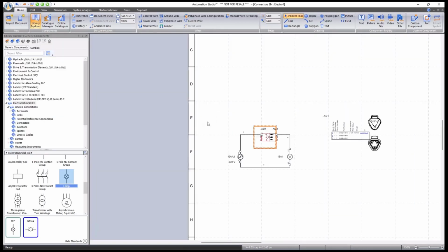We can also see the part number of the pin and the socket. We have wire colors there, though we haven't configured those, and any different part numbers and so on that are in there. And as with all of the reports, you can hold Control and click to follow the link, and that will show you where that component is on the schematic.